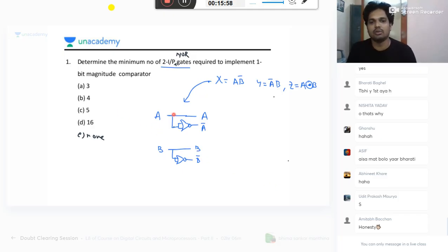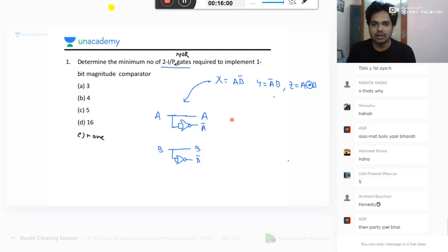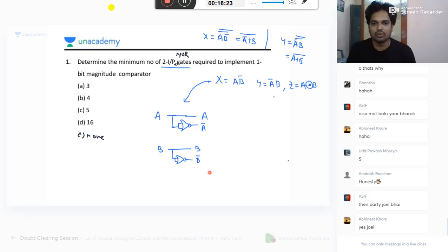Next, very simple question. This one, master slave. We discussed this in the class now. The change in the output occurs when the state of slave is affected. I told this clearly. Slave output is the final output of the master slave JK flip-flop. Change in the input immediately reflected in the output? No, master only changes. Slave will change when clock becomes 0. Change in output occurs when the state of master is affected? No. Okay, master will be affected. Original output will be slave. Both master and slave are affected at the same time? No. Master is positive and slave is negative.